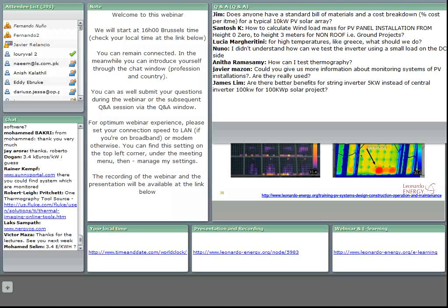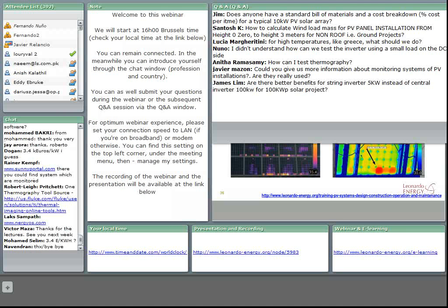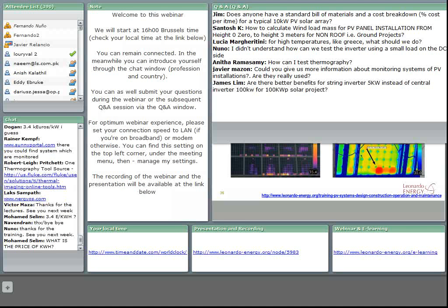Okay, very well. So we have another question, and we are probably going to adjourn soon. What is better for a 100 kilowatt solar project: installing inverters of 5 kilowatts, or just one single central inverter of 100? Well, as we said during the first webinar, where we studied how to choose from the different inverters that we can find in the market, it depends on the number of stages of the inverter. Here it happens more or less the same. We can choose installing various inverters or just having one central inverter.